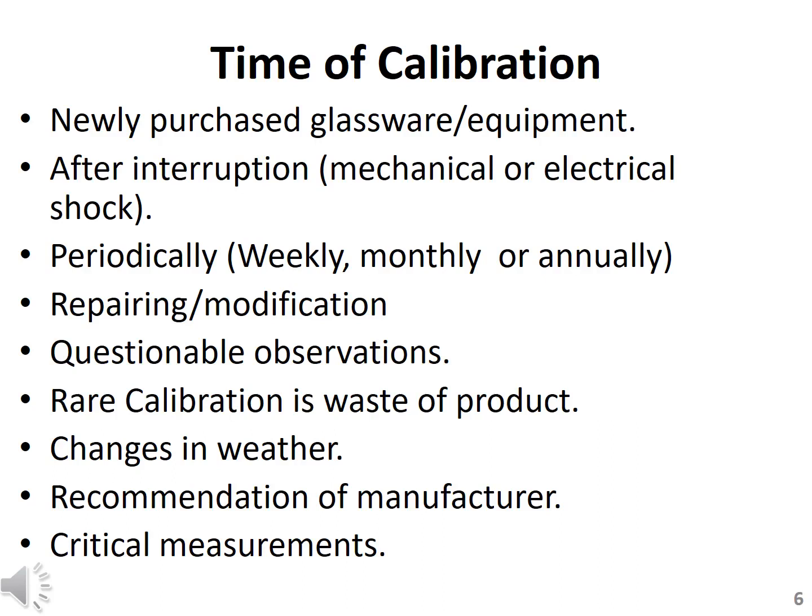Or when the weather changes, then the calibration will also be required. That instrument must be calibrated again. And two more cases: when the manufacturer recommends the calibration, and when you are going to get critical measurements, then you should calibrate the equipment or instrument before starting the process, because you are going to process a critical experiment and you are expecting critical measurements. Then you will be required to calibrate that equipment or instrument.